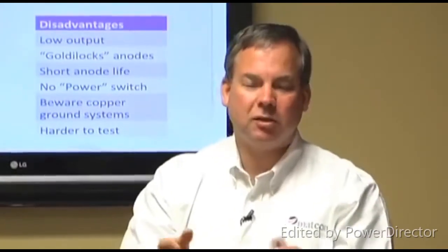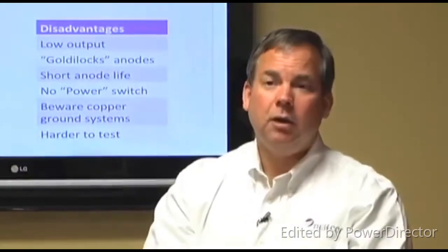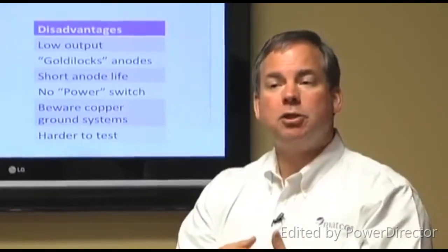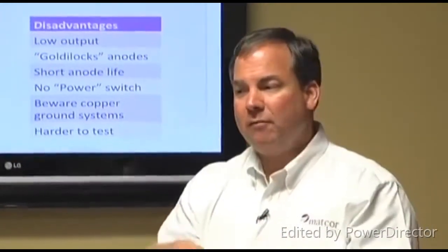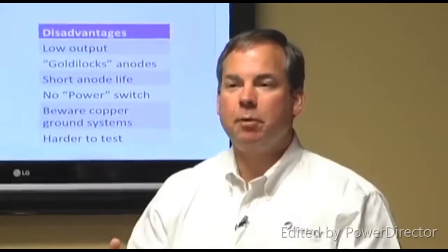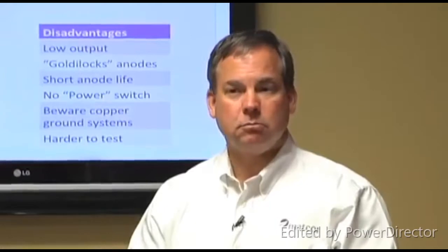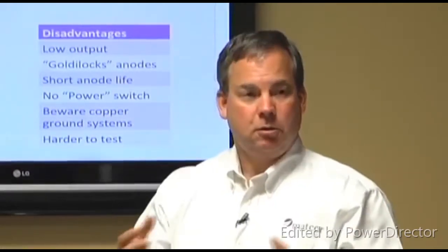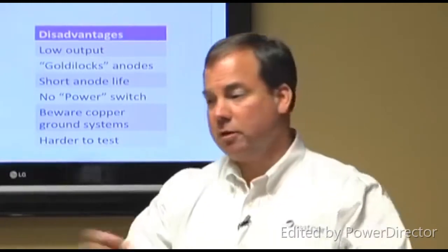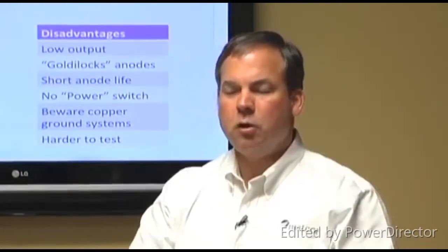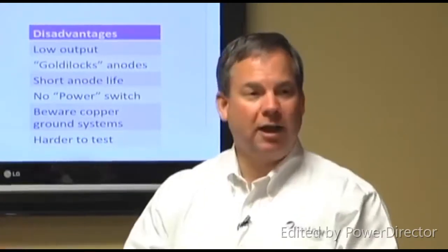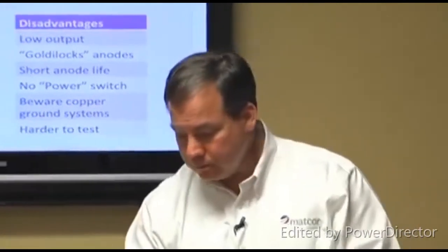Right. Well, it's not the only way to know. It's the easiest way to know. It's also the easiest way to estimate how long the anode life will be, because we know how much the magnesium will consume for every amp of current discharged off it. So those anodes, it's just like a light bulb's rated for so many kilowatt hours. An anode is rated for so many amp hours. So if you know it's doing 200 milliamps, excuse me, when you measure it, you can calculate how long it's going to last based on how much weight it has.